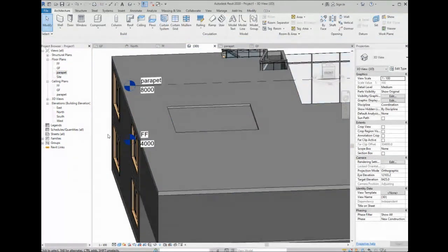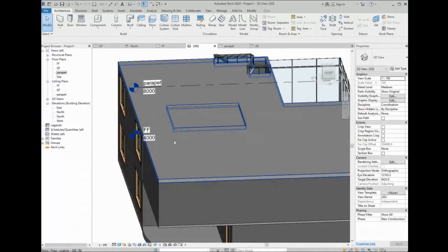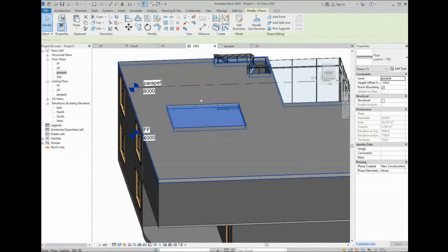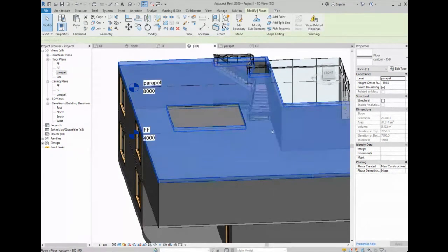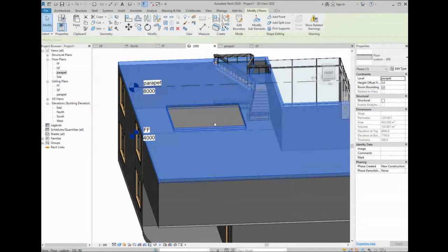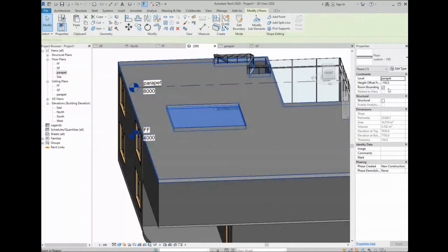I hope that it's clear. So basically, you need to manage the thicknesses. So this is, for example, 300. This is 150, and then you can go down from here 150. So the total for the void and this slab here are the same thickness as this one. And then you will create an opening in this one. So you can double click on it and draw it. And then you will create the slab and you will place it inside. And you will take it down minus 150.